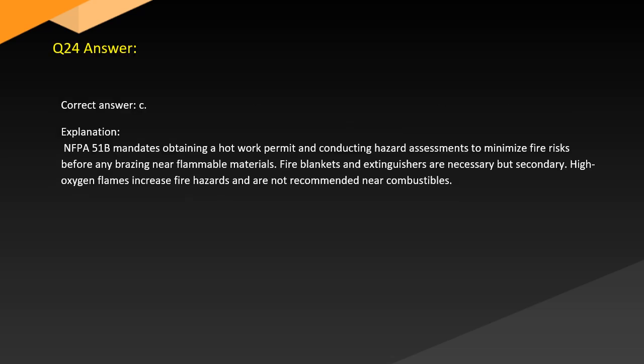Answer. Correct answer C. Explanation. NFPA 51B mandates obtaining a hot work permit and conducting hazard assessments to minimize fire risks before any brazing near flammable materials. Fire blankets and extinguishers are necessary but secondary. High oxygen flames increase fire hazards and are not recommended near combustibles.